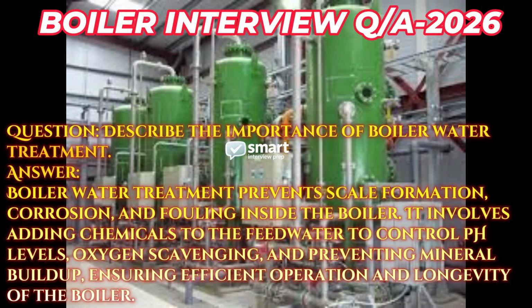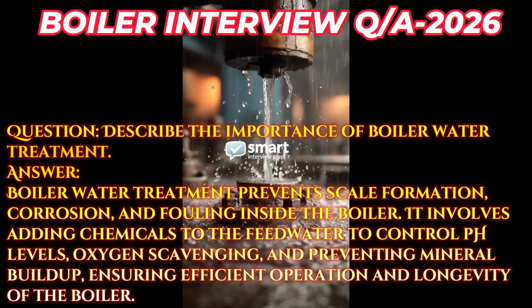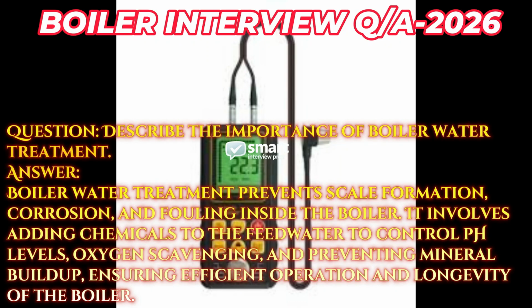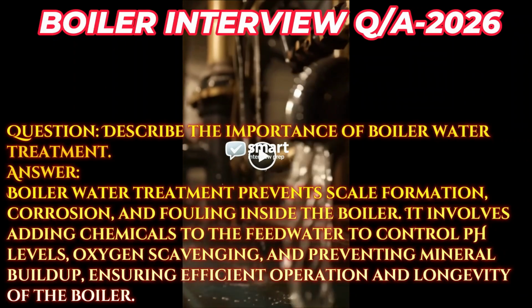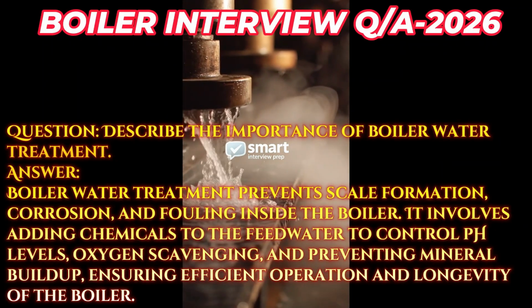Question. Describe the importance of boiler water treatment. Answer. Boiler water treatment prevents scale formation, corrosion, and fouling inside the boiler. It involves adding chemicals to the feed water to control pH levels, oxygen scavenging, and preventing mineral buildup, ensuring efficient operation and longevity of the boiler.